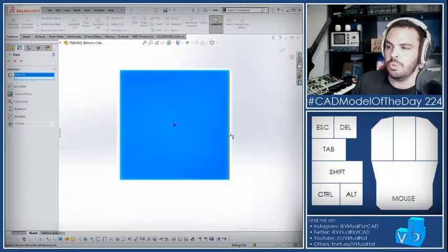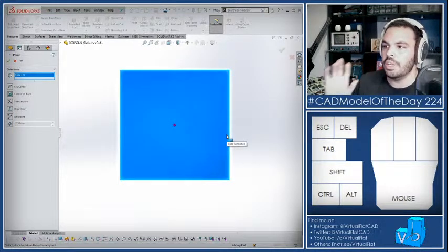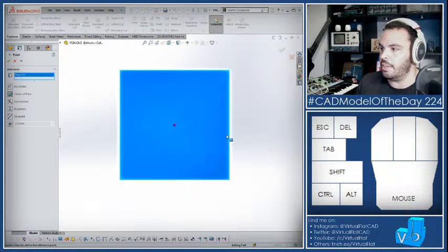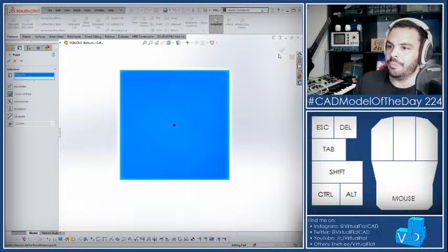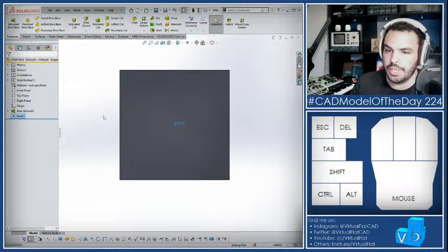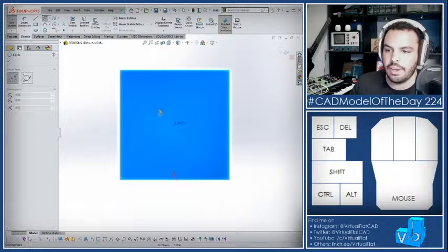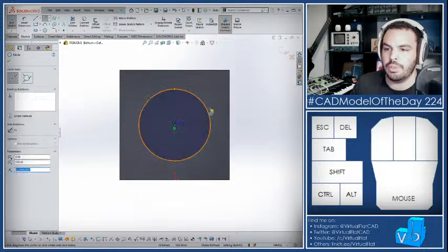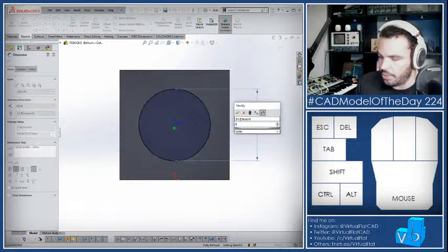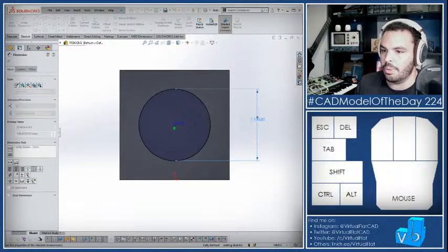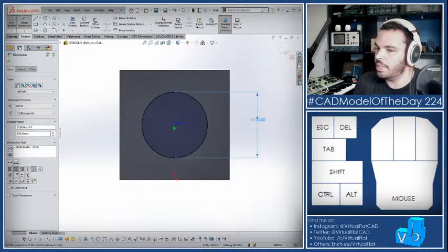I could just drop two center lines and find it pretty easily. But if, for example, you have an octagonal face or a pentagonal face, that could be a little bit trickier to get with construction geometry. And it's certainly not as clean in the sketch. So with that, I have the exact centroid of the face, and I can just drop that exactly where I need it to be, which I think is pretty cool.